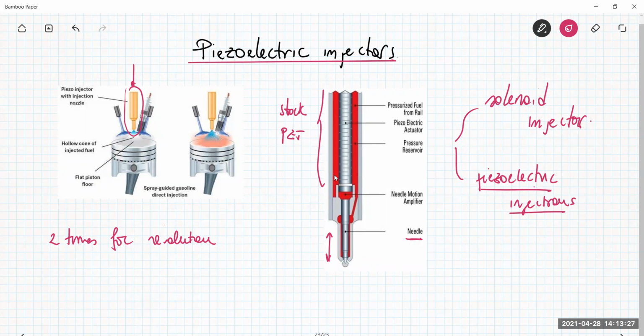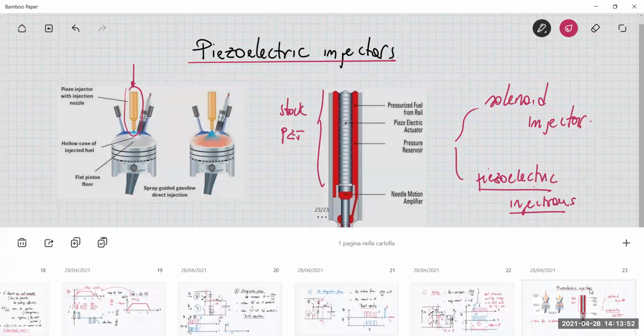The capacitance can be very large, because you have maybe hundreds or even thousands of single stacks of piezo materials. That means you can have several small capacitances in parallel. In that situation you can have large microfarad capacitance to be driven. This is what happens. So let me consider our specification for this exercise.